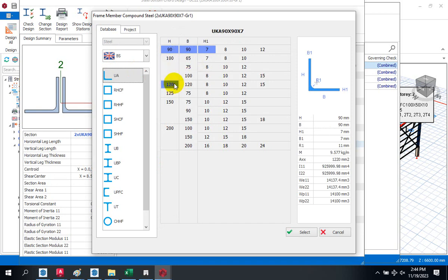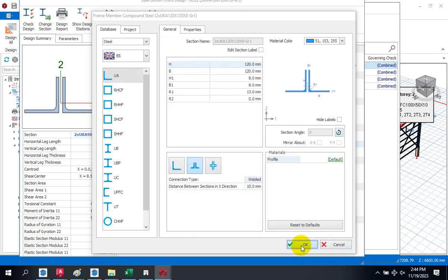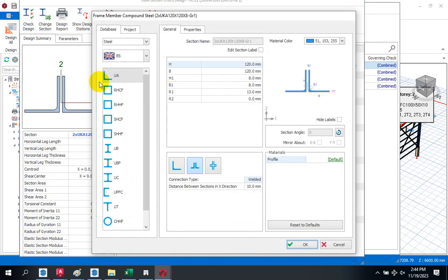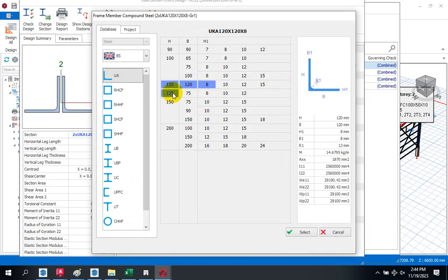That bottom cord, that's what I'm saying. That bottom cord sometimes always requires a higher cross section. Yes, so I'm supposed to increase it. So if I increase it now, you see the value will drop to 364. So I can go further to keep increasing that cross section until I have a suitable cross section that fits what I am looking for. I don't know if it is making sense.